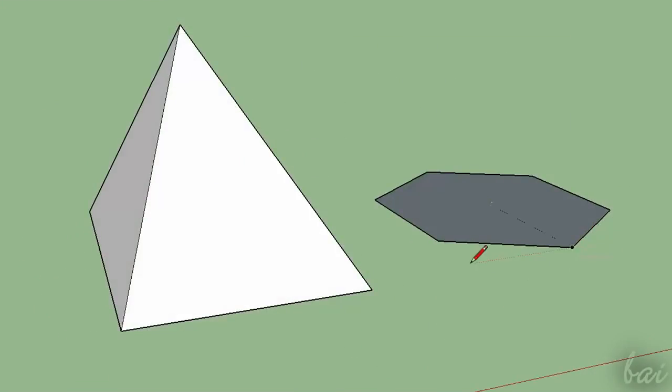SketchUp helps you with snappings to some key points in order to make drawings easier. Below your pointer, different nodes may appear case by case. Endpoints, midpoints and centers are usually represented through small circles, points along a path through squares, and points along a face or surface through rhombuses. Also, dashed guidelines can help you draw in parallel or perpendicular to other nodes.